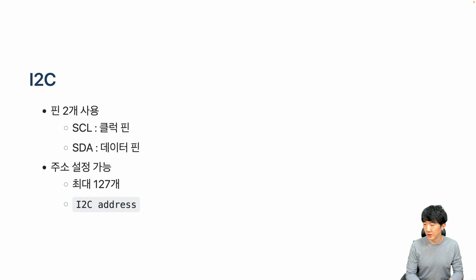First of all, I previously gave a lecture related to I2C in another course, and here I will very briefly explain it, assuming you are familiar with it. In I2C, you need a couple of pins. SDA is essentially the data pin, while SCL is basically the clock pin. Data is exchanged based on the clock, which is essentially determined by SCL. You can also set the clock, but generally 100 kHz is used.